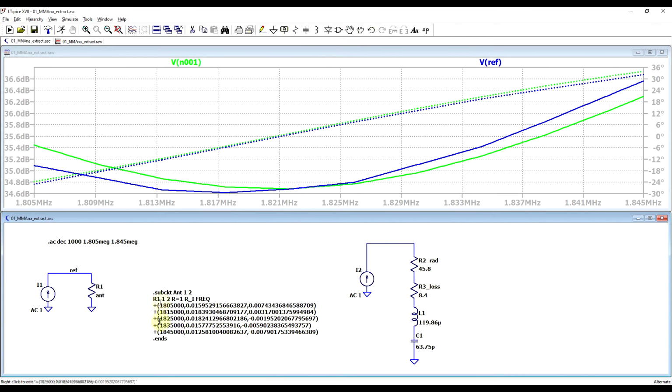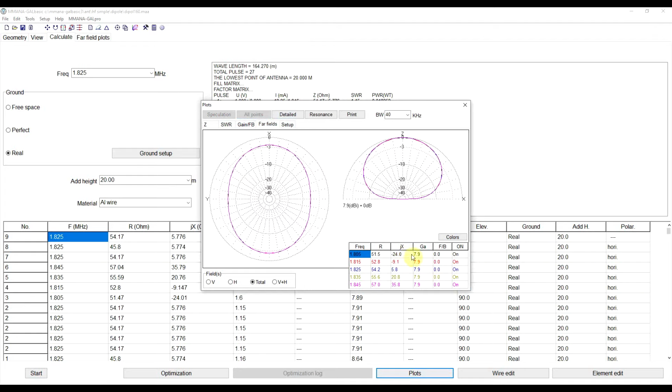So you do get differences. We are not modeling the frequency-dependent resistance, but this new model will now be usable in a transient simulation. Now, if you do need a more accurate model, you can always create single frequency models. So just take the impedance value from a given frequency and model that. And the model will then be valid for that specific frequency.